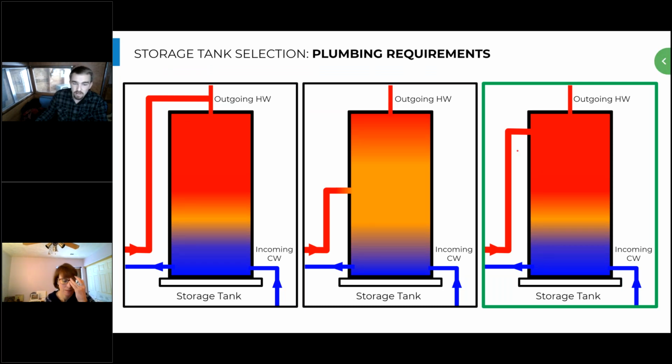Yeah, so a lot of times we will see tanks that are a lot more like this as a standard tank. Maybe this middle connection here is actually located down here, which is not ideal for a heat pump. So the custom top connection that I would refer to is having a heat pump connection up here as close to the top of the tank as possible in this horizontal manner, while you still have a top connection that can send hot water out to the building. Right, so you have 4 connections total on this tank, where in some tanks you have 2 and some tanks you have 3. The Sanco 2 tank already has these custom connections, so you can just buy that as a heat pump water heating tank and you're covered there.